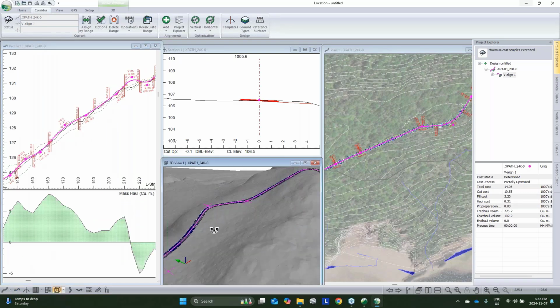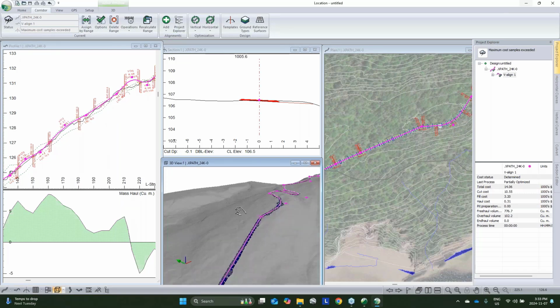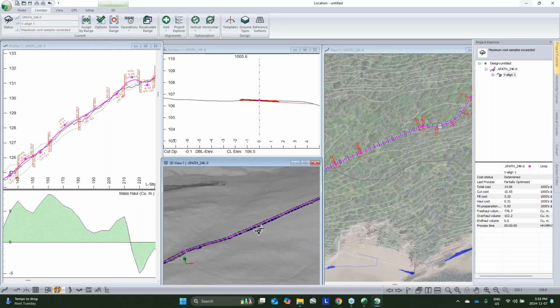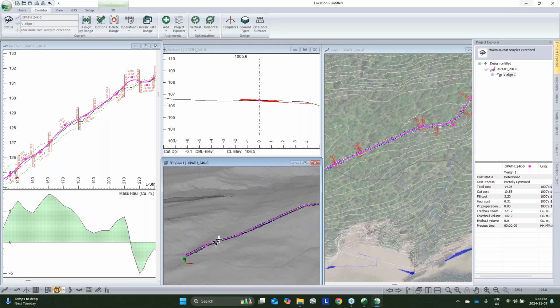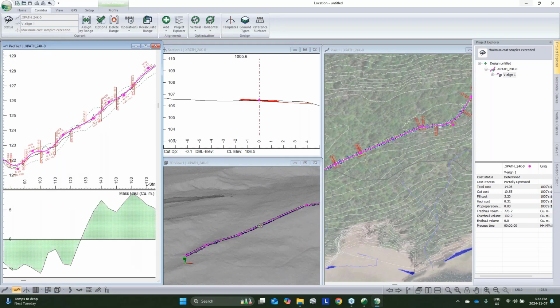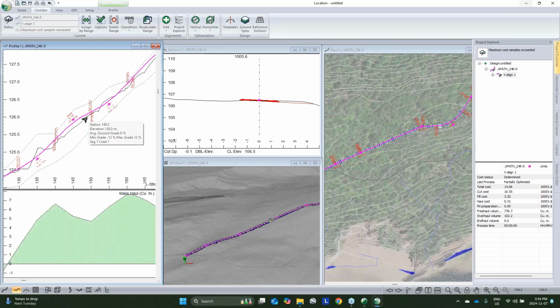So here, if we want, let's go back to, so I've got a pretty long stretch here where my trail is descending. If I want to help break that up and allow some flow across the prism, we could force a grade reversal.